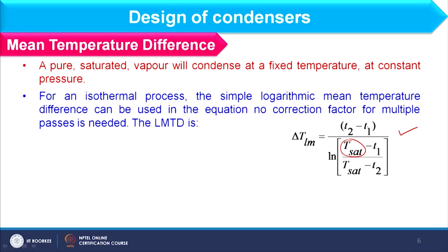So, in that case we can have a non-isothermal condition on the condensation side along with the same non-isothermal condition on the coolant side. If you see the profile, it will be like this when it is co-current, and like this when it is counter-flow pattern. In that case we may get the chance where temperature cross occurs, and if this happens, it will not be good for the design of the condenser.